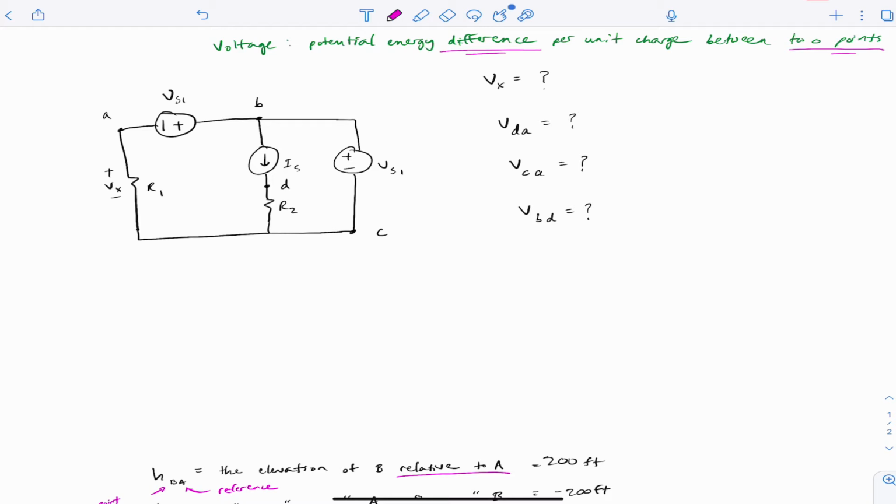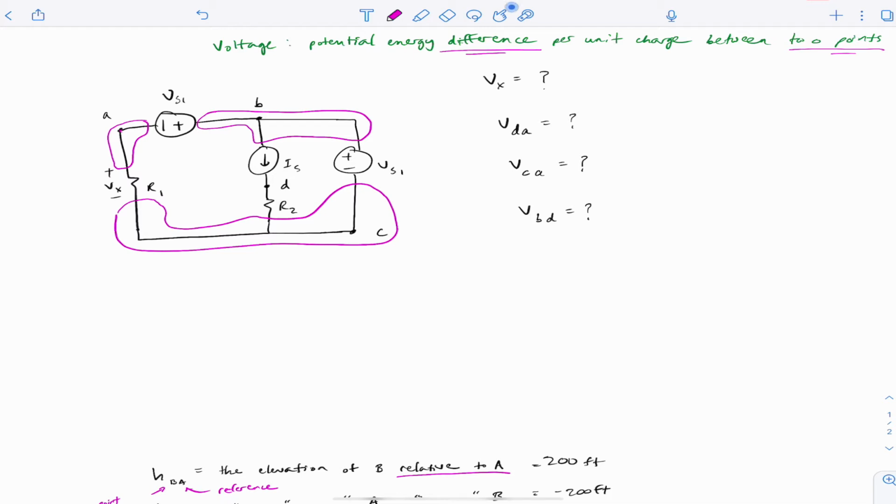Armed with this knowledge in this previous analogy, let's attack this circuit. So it's helpful if you identify the nodes. So this actually is A. It's not just that little point here, but it's that entire electrical connection is A. And that's all at one voltage. It's all one elevation, if you will, in the potential landscape of this circuit. Node C, node D. Again, each node is at its own elevation. Any 2 points on that node are all at the same elevation.